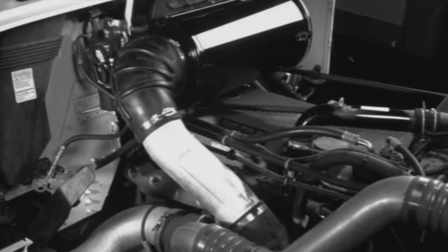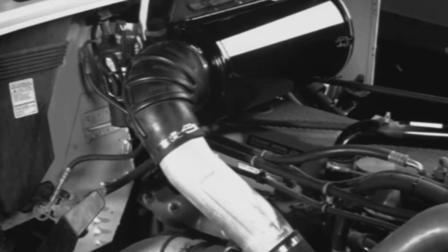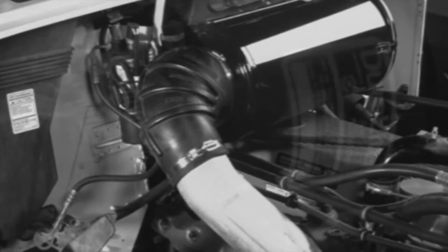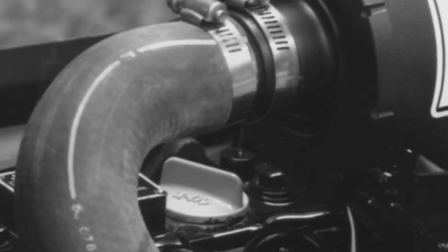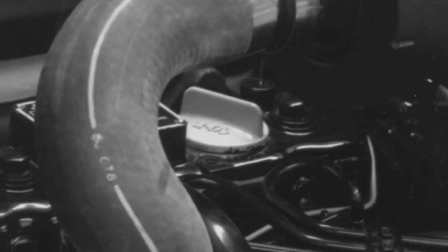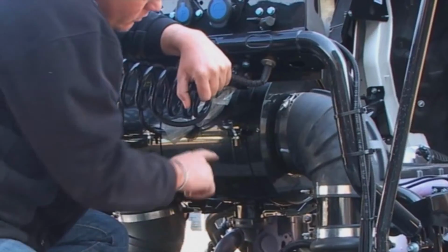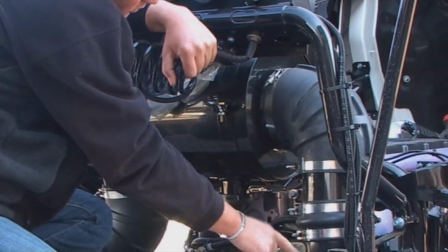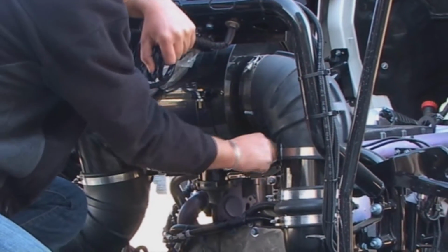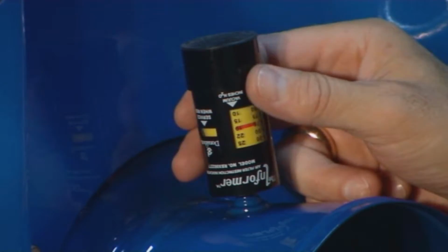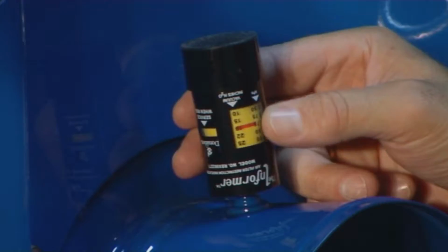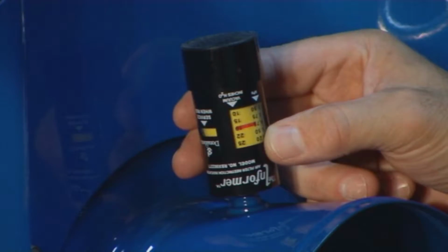That's restriction. Similar to the drinking straw, any changes in flow direction in the air intake system created by rubber elbows, reducer pipes, pre-cleaners, and inlet hoods can cause restriction. Keeping restriction measurement in mind will help you as you design or work with your air intake system. Restriction measurement also plays a key role in effective air intake system servicing.